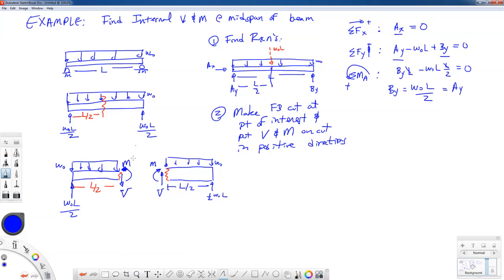So now in order to find the shear force and bending moment, let's use this left diagram. If I do the summation of forces in the y direction, I'll have plus 1/2 W0 L minus the statically equivalent force from this distribution. You notice how I'm dashing it in to indicate an equivalent force.